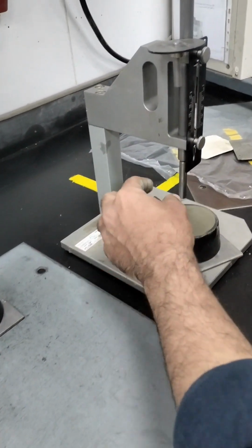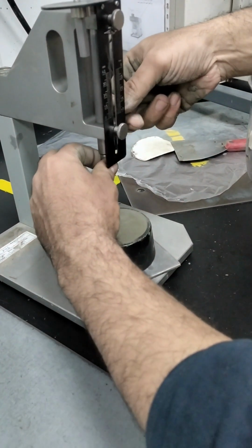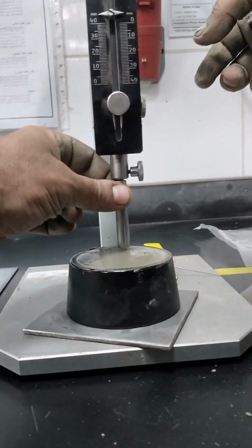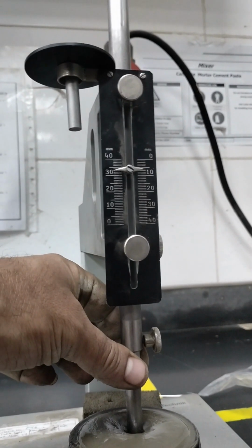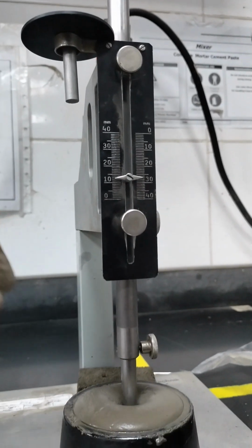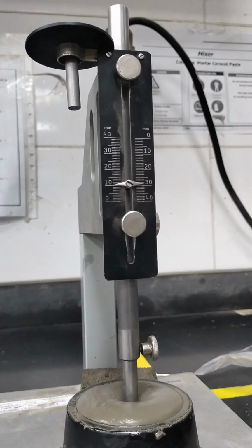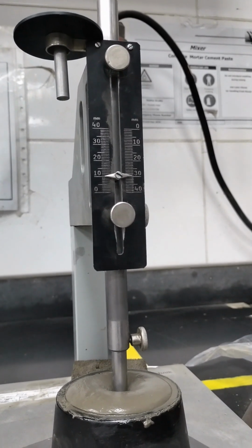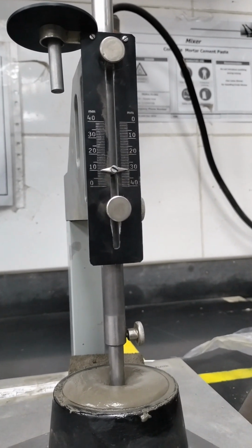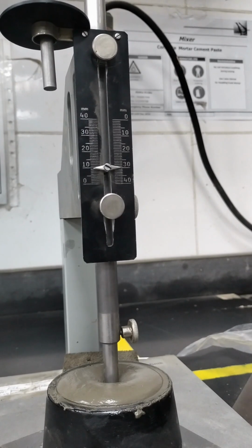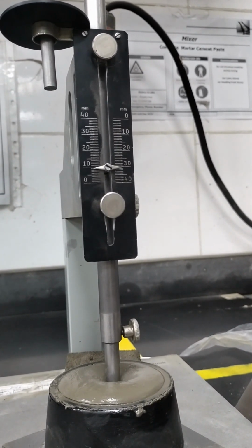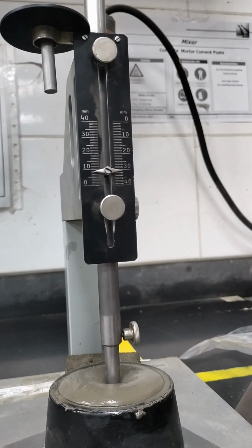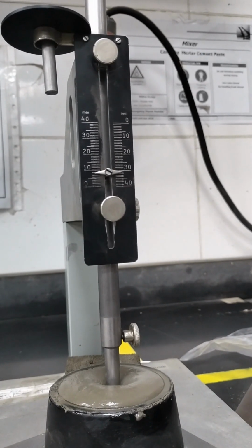Immediately after leveling the paste, transfer the mold and base plate to the Vicat apparatus and position it centrally under the plunger. Lower the plunger gently until it is in contact with the paste. Pause in that position for between 1 second and 2 seconds in order to avoid initial velocity or forced acceleration of the moving parts. Then release the moving parts quickly and allow the plunger to penetrate vertically into the center of the paste. The release of the plunger shall occur 4-10 seconds after 0 time.